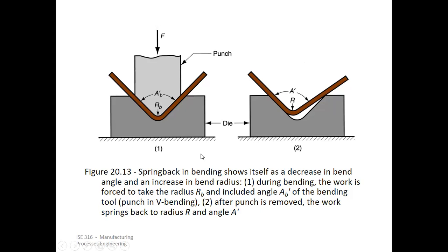So you have to take into account the spring back and change the final angle. If you want the angle to be so and so, then considering spring back, you have to either increase or decrease that angle, so that the final component is as per our specifications and not erroneous because of the spring back. So consider the issue here, that is spring back, so that we can get the required angle and the radius, etc., without failure of the sheet metal.